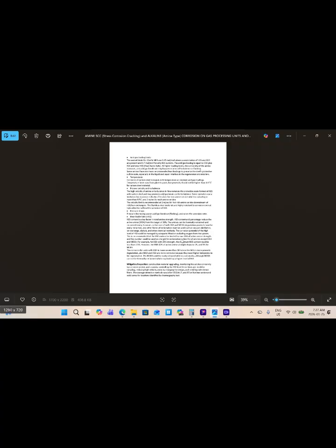The corrosion potential of a high level of HSS could be managed by adequate filtration and excluding oxygen from the system. So oxygen must be removed and filtered from the system. It is recommended that the HSS content be limited to a maximum of 10% of the active amine strength.